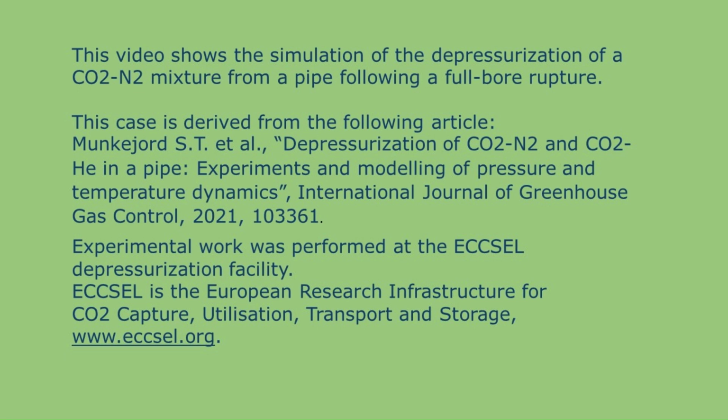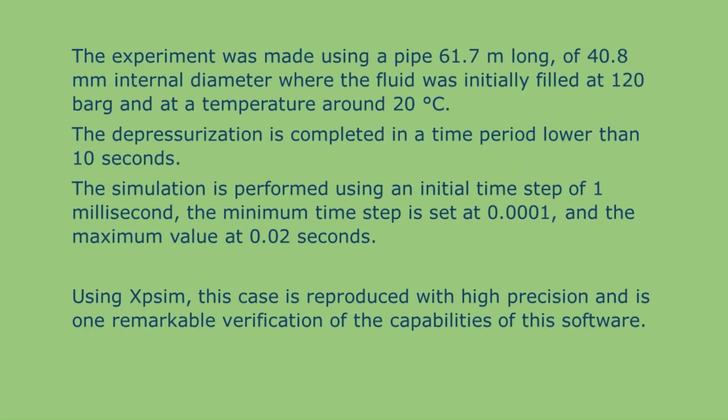www.eccell.org. The experiment was made using a pipe 61.7 m long, of 40.8 mm internal diameter where the fluid was initially filled at 120 barg and at a temperature around 20 degrees Celsius. The depressurization is completed in a time period lower than 10 seconds.